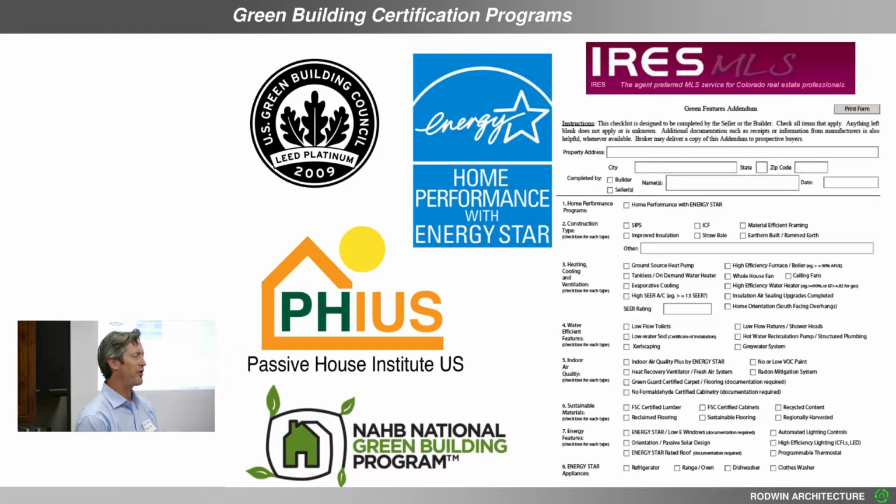Most passive houses, it's a German program, and they tend to be focused on more of the high-tech rather than the low-tech side. So it tends to be things like triple-paned windows because they're incredibly highly insulated. Their U value is super, super low. And we'll talk about U value in a moment. A lot of foam in the walls and outside the walls to help really insulate the house. Those tend to be strategies associated with passive house. I don't know of any passive houses that are straw bale, but theoretically, a straw bale house could be a passive house.